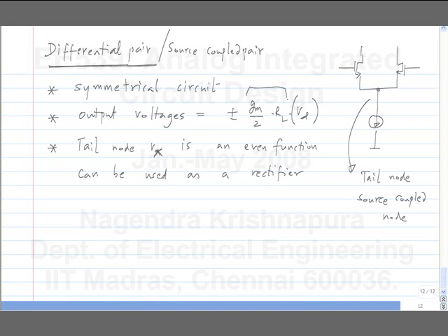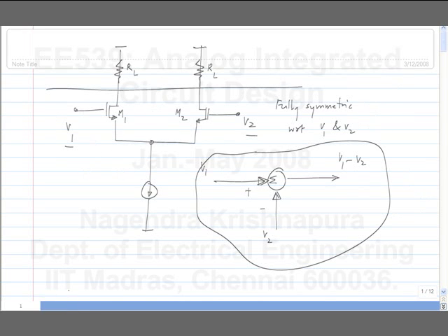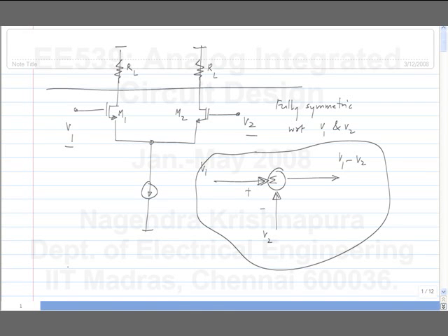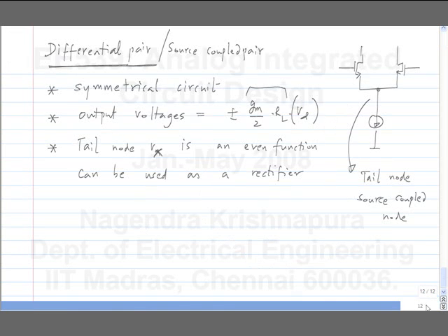So what happens is that we use the voltage buffer to couple to the source of the common source amplifier. If the voltage buffer was ideal, that is it had 0 output resistance, then all of the input difference would appear across the common source amplifier and you would get Gm as the proportionality constant between the input difference voltage and the current in the transistor.